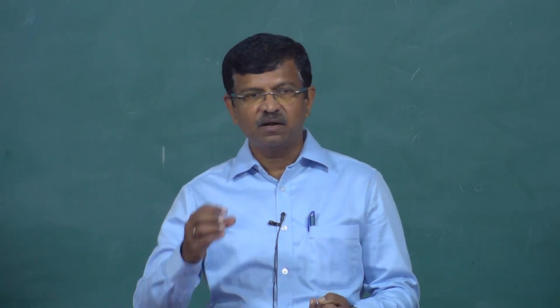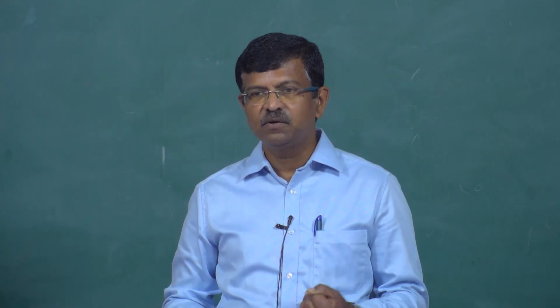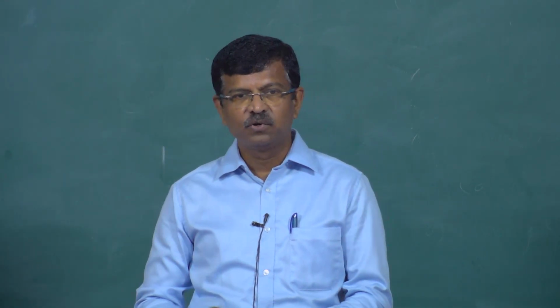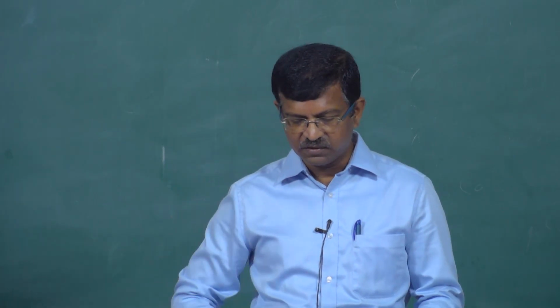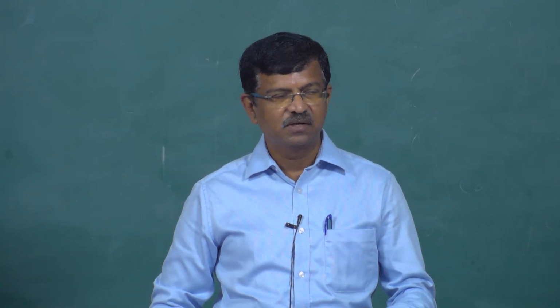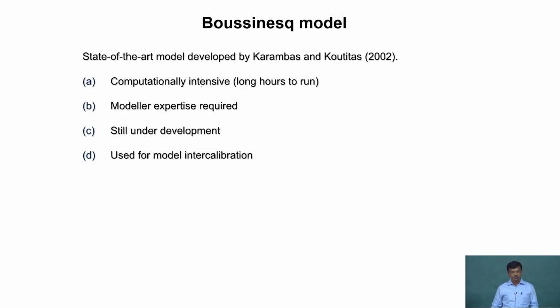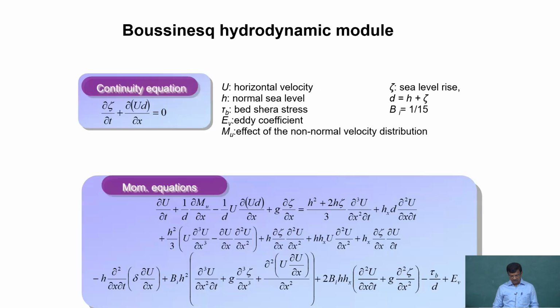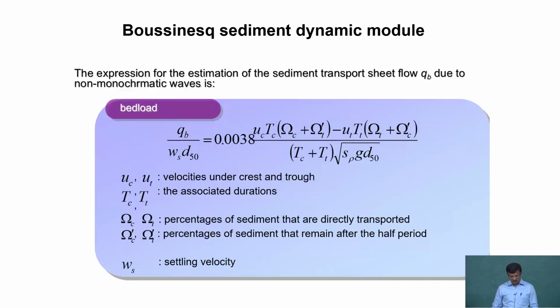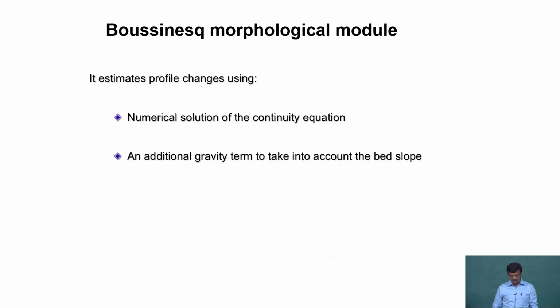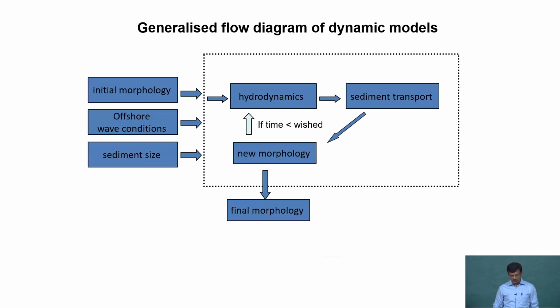That means we can add on the morphological module, easily fit it into a Boussinesq model and drive the sediment transport. That is one of the advantages of it, and many of the recent commercial packages also have the Boussinesq modeling system, but how we are going to integrate it into the entire system is very important. So the suspended load, bed load, etc. I already mentioned to you. The same thing is there for every other location also, that we can comprehensively make it a Boussinesq morphological module, but the morphological module is a standalone which you can fit into any other locations or any other system.